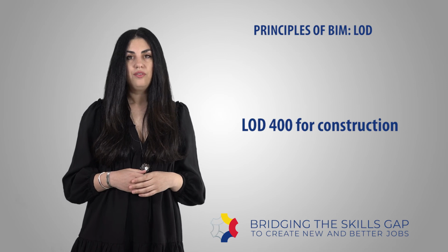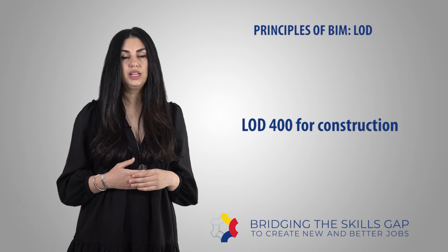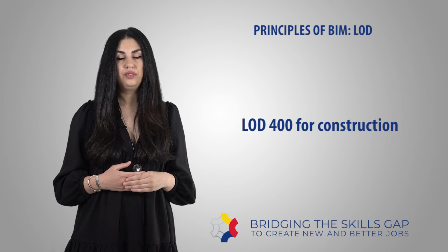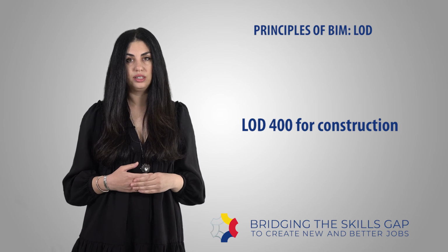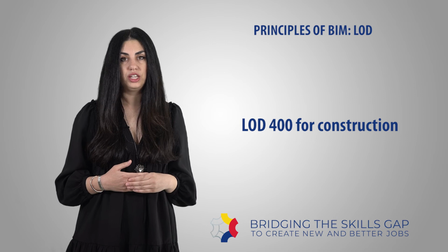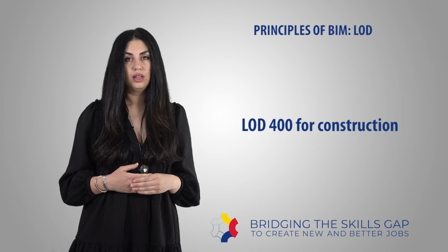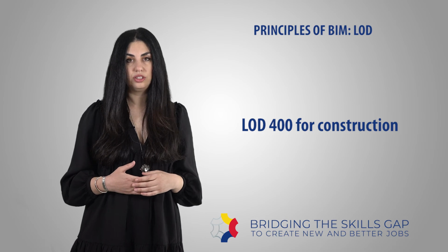LOD 400, fabrication and assembly. Model elements are modeled as specific assemblies with complete fabrication, assembly, and detailing information in addition to precise quantity, size, shape, location, and orientation. Non-geometric information to the model elements can also be attached.